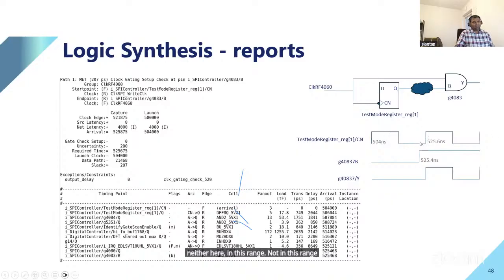It should appear after this falling edge, but before that rising edge, so anywhere in this timing window. That's why you see this flip-flop is negative edge triggered. So this Q pin will change only after this falling edge, before that rising edge. So this is the sweet spot where you can turn on the clock gate without distorting your clock network. I hope you understand that. It's pretty straightforward.